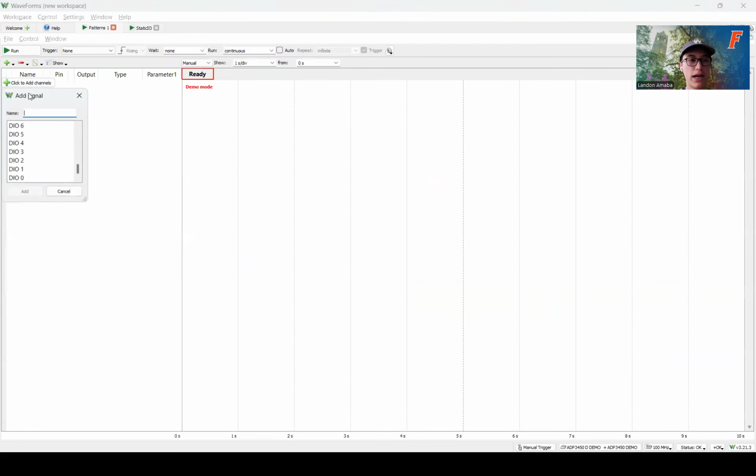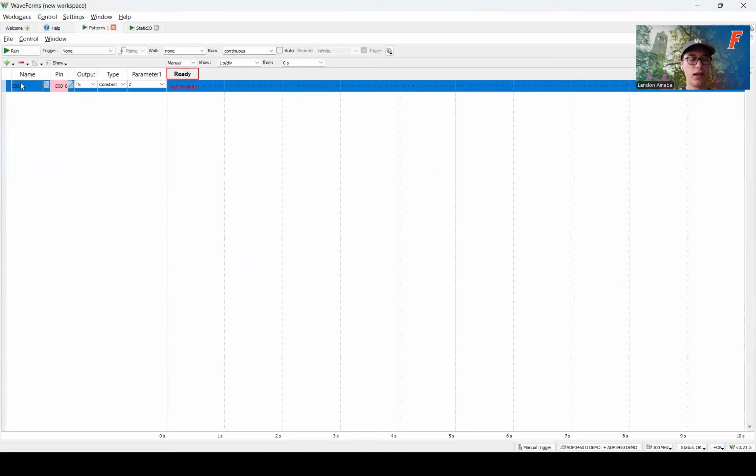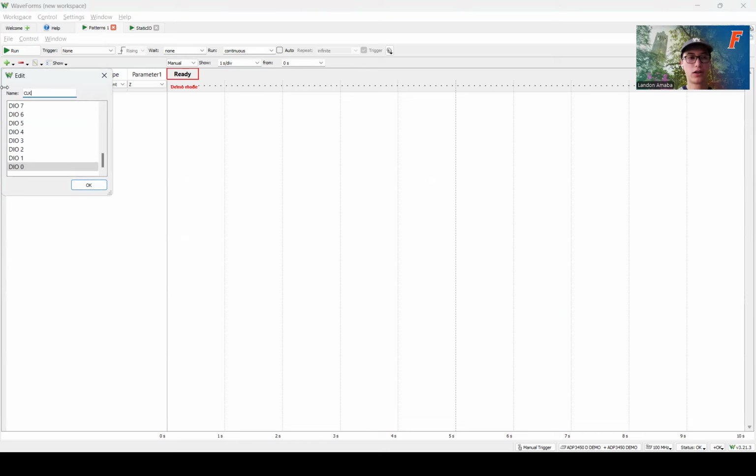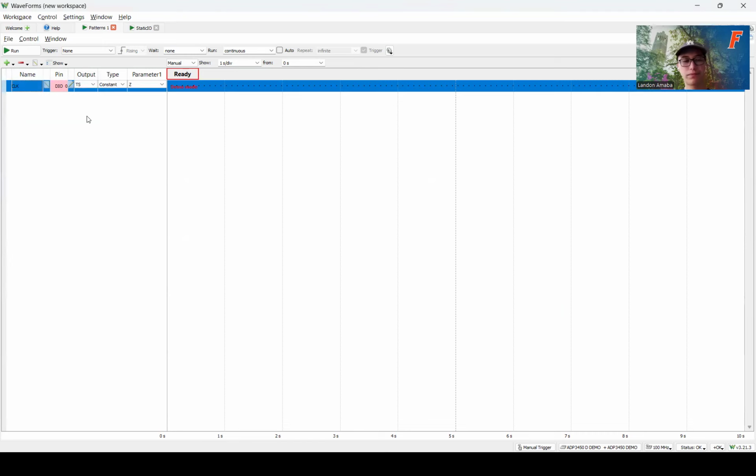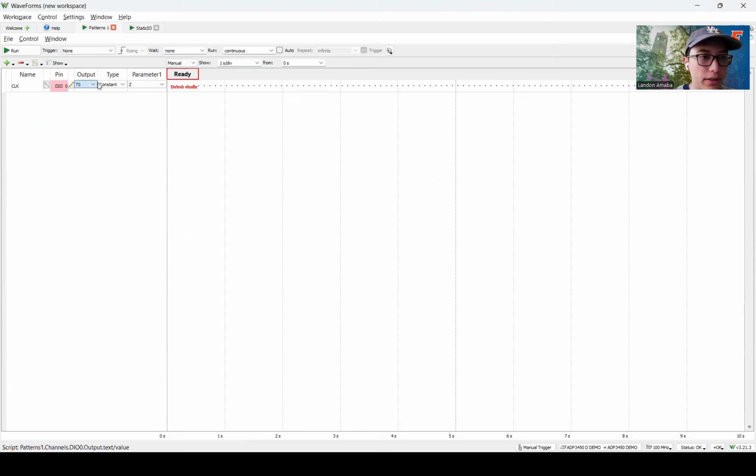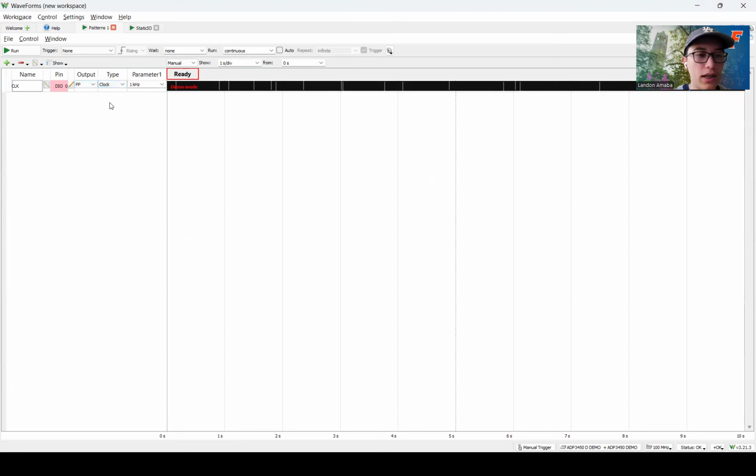So I'm going to start just by adding a signal. I don't have a current circuit wired up, so I'll just use an arbitrary value. Here, we'll just call this our clock value. And this will be clock right here. And in the lab doc, it specifies 0.5 hertz, which means it'll clock once about every 2 seconds.